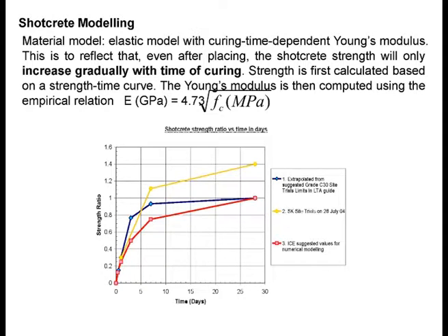Now, the rate of hardening is very important because the cycle is 1 to 2 meters a day, and your gap is 1 to 2 meters. Your shotcrete has to build up sufficient strength before you can move forward. You get what I mean? So what is more important is not just that you leave a section uncovered, but even the section that is supposedly covered but has not reached full strength, and they are still deforming. So the question is, how does this affect the whole situation?